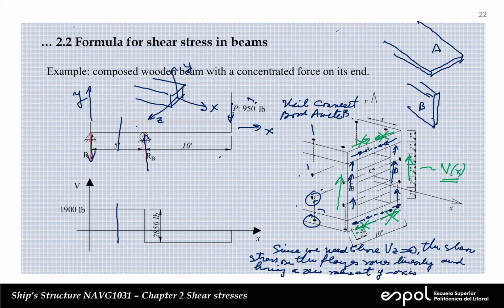So you're seeing that you have a force pointing downward in the y direction. So you can imagine any distribution of stress on the section, but you integrate those stresses, you will get internal forces. And the only internal force that we are trying to recuperate here is V. And V points in the upward y direction.